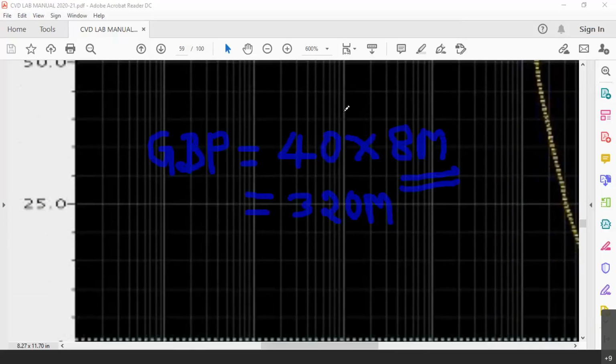Now if you want to increase the gain, you will have to compromise on the bandwidth. Let us say you want to have an 80 dB gain. Right now this amplifier is having 100 times gain. If at all we want to use it as a pre-amplifier for a satellite signal, a gain of 40 dB is nothing there. We should have a multi-stage pre-amplifier in such cases.